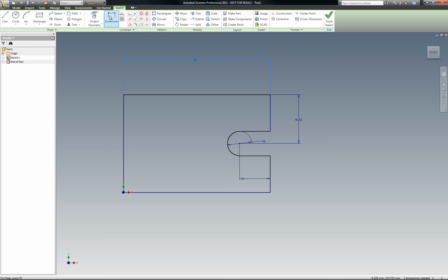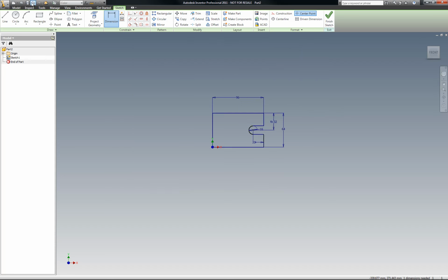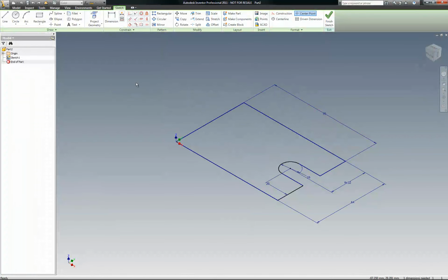Okay. So I'm going to undo this. Actually, I'm going to put that up here. I'm going to redimension this. So I'm going to go from this side to that side. Okay. And that is now D5. So I make this D5. There you go. And then when I take this and change this to 100, that will stay centered. So let's go back to the 64, and it's just something you can do. You don't have to do it, but later on it'll pay off. Parametric will pay off later on when you're doing bigger projects.